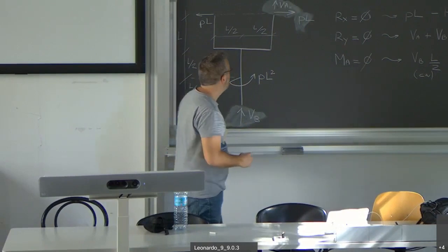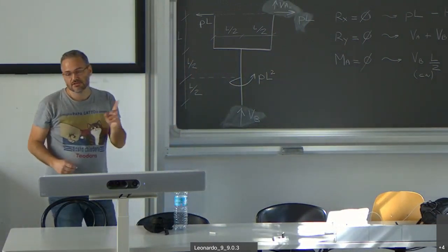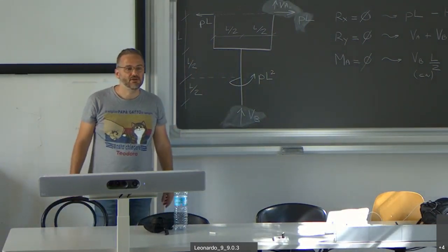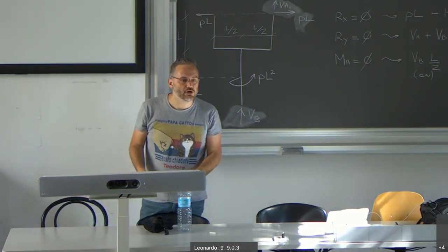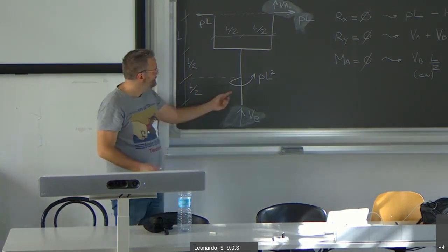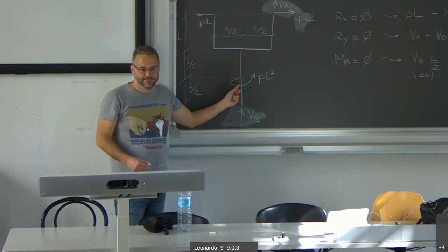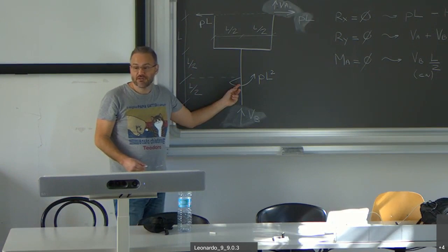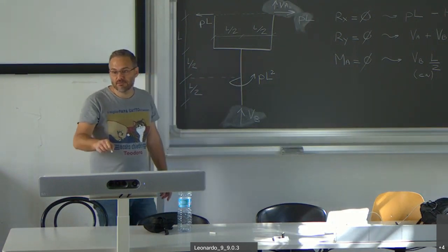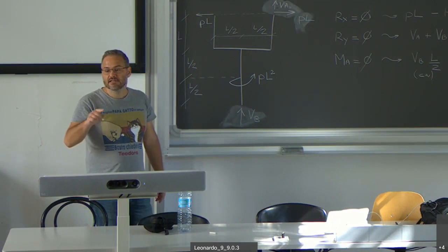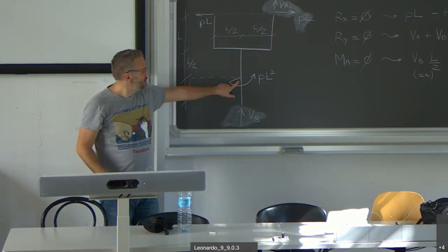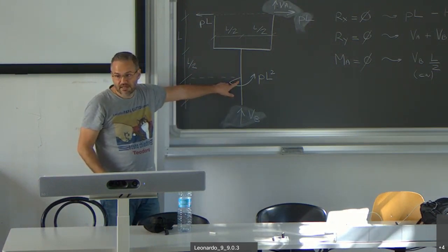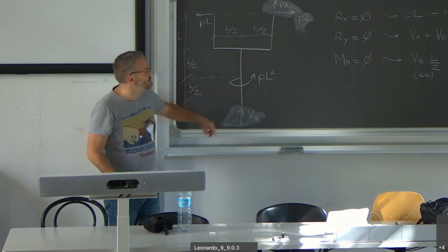Careful, because in this exercise there was a peculiarity which didn't occur in the usual written exams. There is a concentrated moment, which has to be taken into account when you write equilibrium equations. Of course, it does not contribute to the translation equilibrium, but it plays a role when you write equilibrium equations.